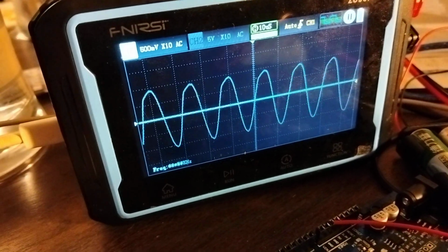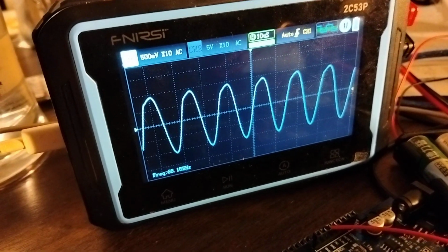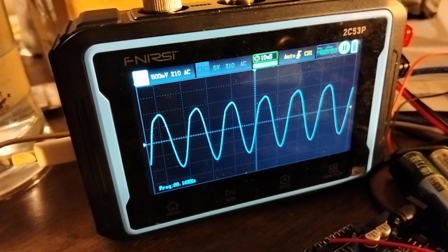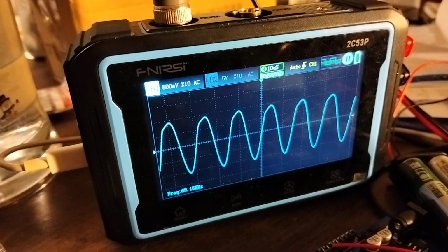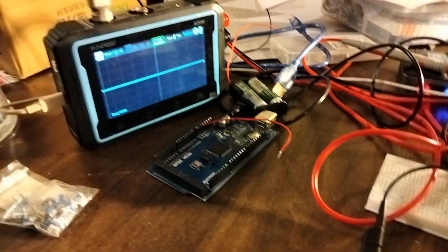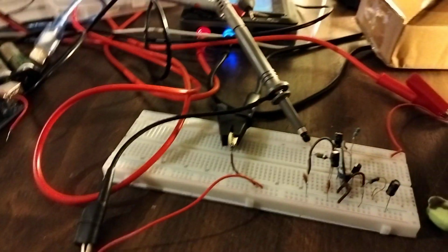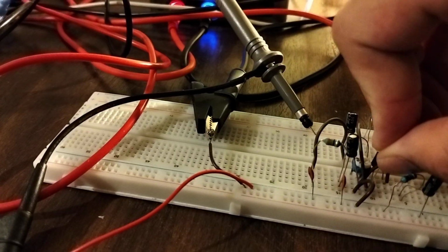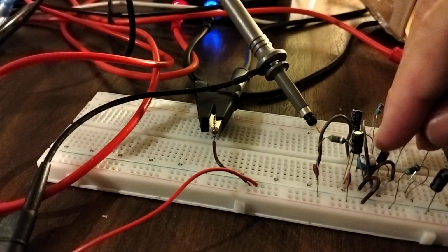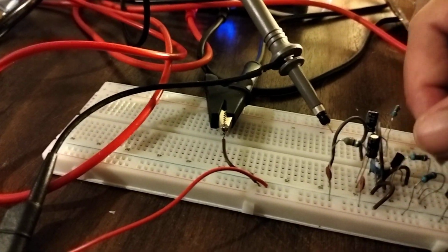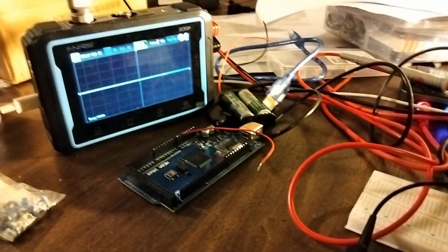That's because when the gain is too sharp, it can slam into the supply rails at the very top, and there's not a gradual enough roll off to the unity gain of 1. So by increasing the unbypassed resistance in the emitter to 100, it fixed this problem.